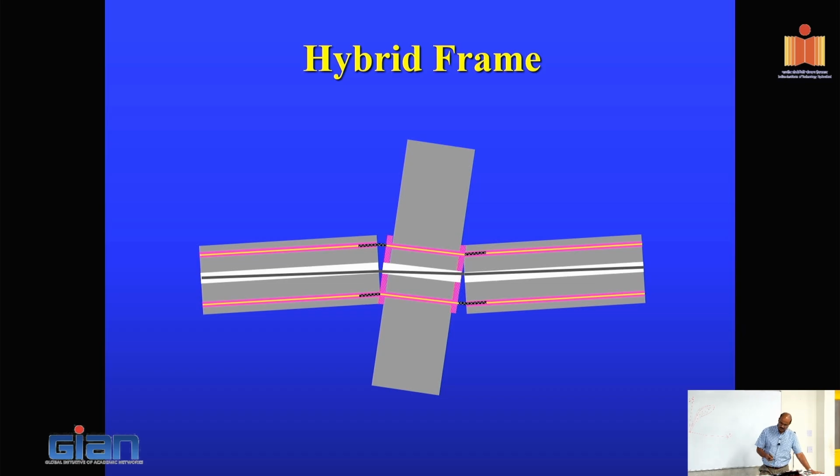To overcome that, this darker line indicates that portion of the bar was debonded. It's basically like putting duct tape on it to release it from bonding. That allows the gap to open up and the strain to be distributed over 150, 200 millimeters, which is something you can calculate.